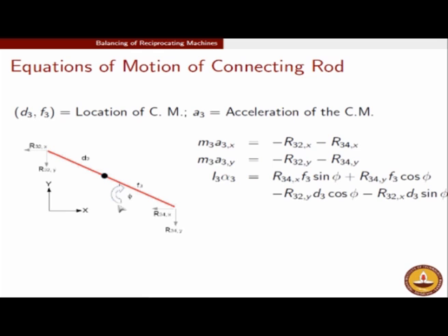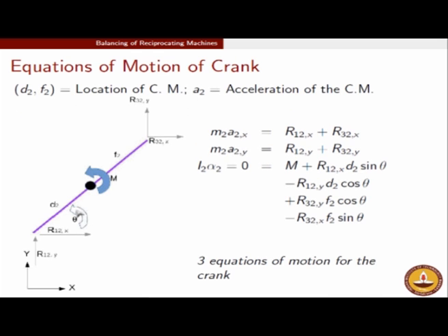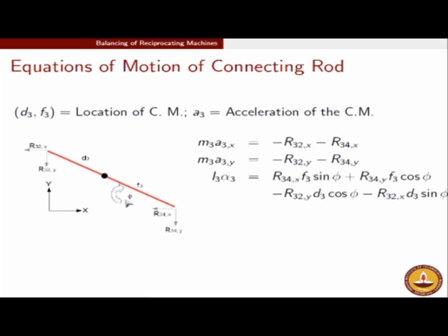But the reason we have this discrepancy between the crank and the connecting rod is that our kinematic variable is theta in this direction, whereas it is phi in this direction. So if you want your dynamics to be commensurate with the kinematics, then you should have it in this fashion, else you have to take the kinematic variable in this way in case you wish to make your dynamics have a consistent moment between members.